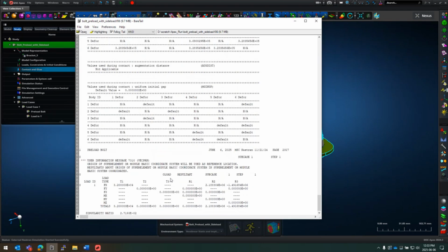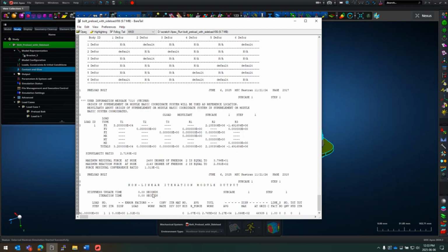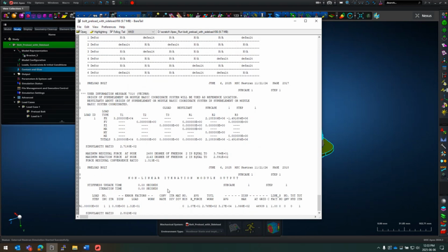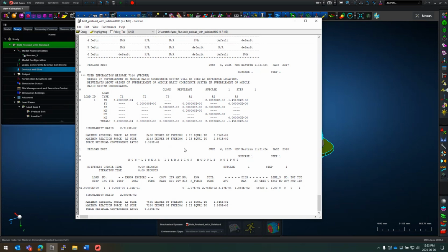So there's the F06 file, and as it's running now, it shows you some basic info. I just want to step slightly back just to understand what this file says. We're now busy with the nonlinear stepping. It's trying to reach 100% of the full load for load case number 1.